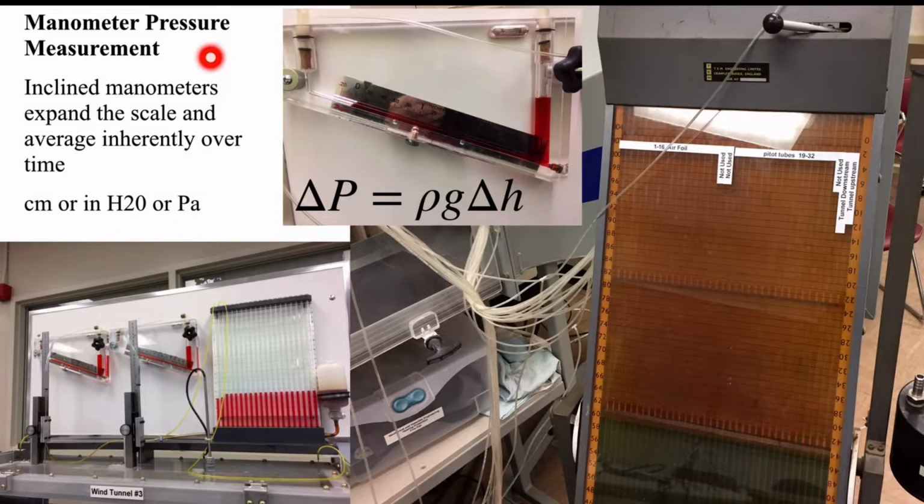The other way we can measure pressure is using a simple water or oil manometer. If you take a simple vertical manometer, delta P equals rho g delta H, back from fluid statics in Fluids 1. If you incline the manometer, you get more motion along the length of the manometer tube for a given change in the elevation, and the result is you can get more sensitive measurements. You can measure in centimeters or inches of water as a pressure indication, just the height of water on the manometer tube, or you can convert that to pascals, an actual pressure measurement, with delta P equal to rho g delta H.